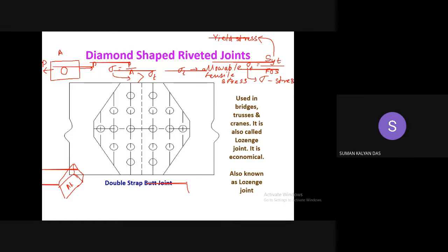If somebody asks you to determine the yield stress, although the value for aluminium is available on the internet, you can just search it and get it. But suppose you are working on a critical project where the exact yield stress has to be determined. Based on the processing of the aluminium raw material, there is batch to batch variation. So it is always better to test directly the material you have in hand rather than believe the value from the internet.